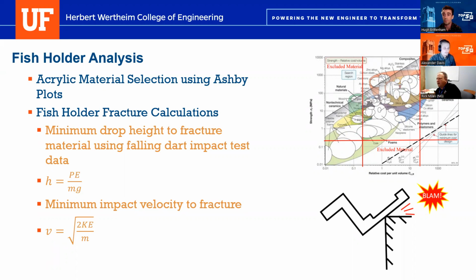So I would expect that your max loads are going to be handling loads. So you just want to investigate typical handling loads for this sort of structure. It's probably just a few pounds or something, but that's what I would expect to be your driver from an analysis standpoint, what sort of handling loads you'd expect to experience with this particular structure.